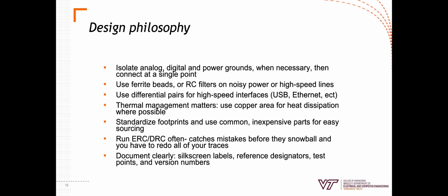So, thermal management. Some chips that take in a lot of power emit a lot of heat, and you can use vias to spread out the heat signature of the board or the chip, and you can use the PCB as a radiator. If you use a bunch of thermal vias, which are just vias intended for heat dissipation, you can spread out the heat signature on both copper layers so that the IC can vent excess heat to the PCB and spread it out.